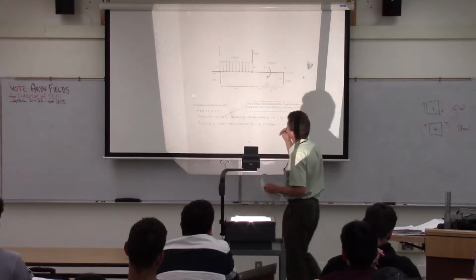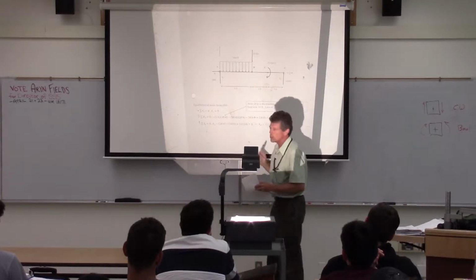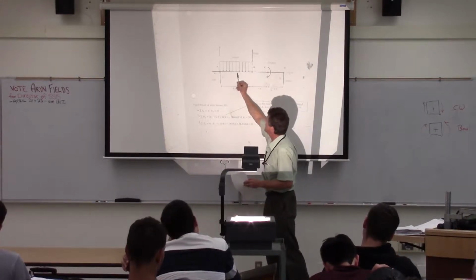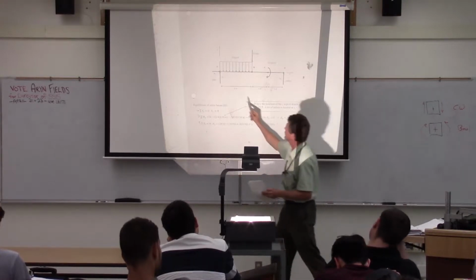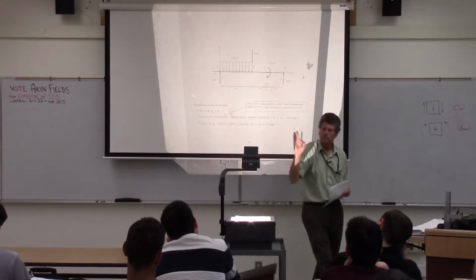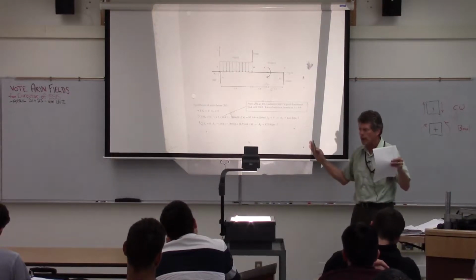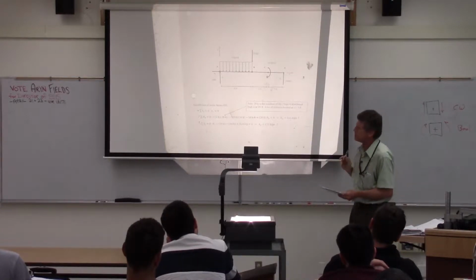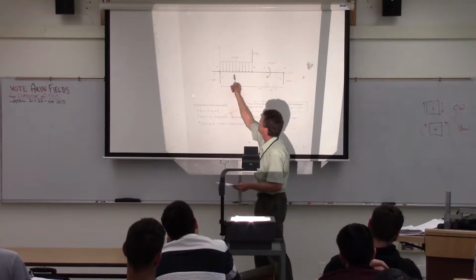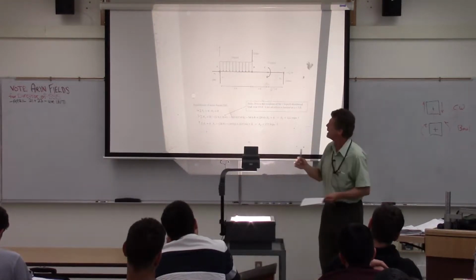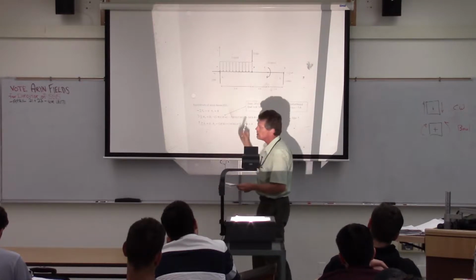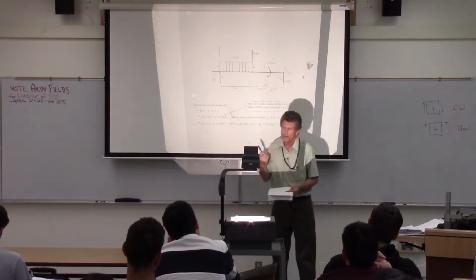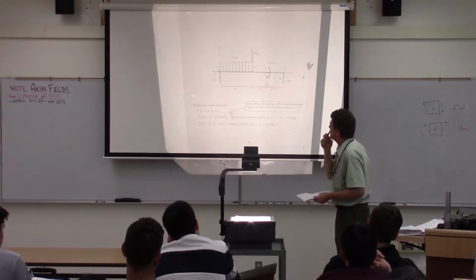Now, we're going to be making cuts, and the first cut that I think we started talking about on Thursday was between 0 and 10 feet. And what we're saying is I know what's going on between 0 and 10 here. My uniform load is going to be uniform wherever I cut it, at 1, 2, 5. But I can do a little calculation. It's going to simply be 2 times whatever that distance is to give me that value there. So I know that I can make a cut anywhere in here, and as long as I express my load in terms of that x value, which we did, then everything's valid between 0 and 10.